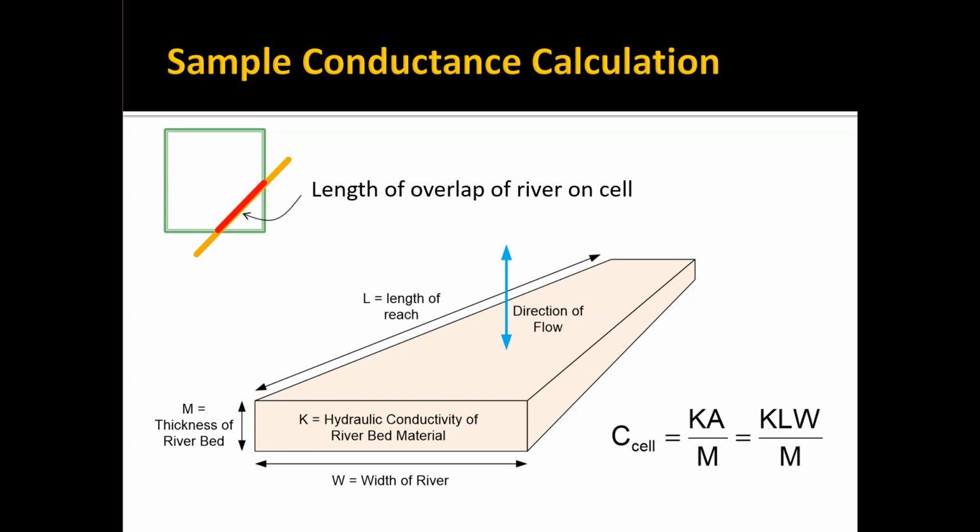Okay, so this conductance term is used not just by the drain package, but by several other packages as well. But now we have an introduction, and through the exercises and homework assignments, we're going to have a lot of opportunities to calculate conductance. And so it's something that should become second nature. Again, you just think back to Darcy's law, K A over L, and it's pretty easy. It's a pretty simple thing to calculate.